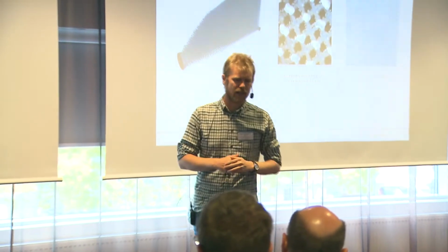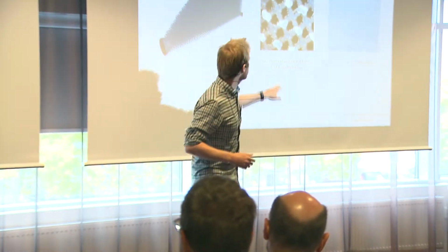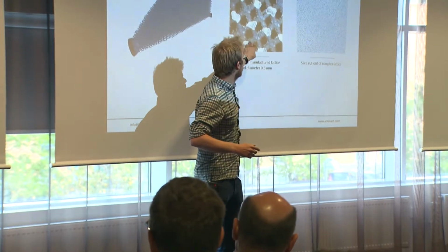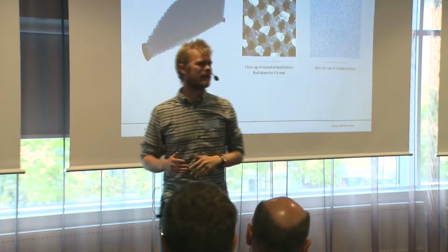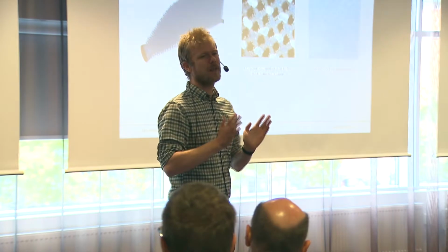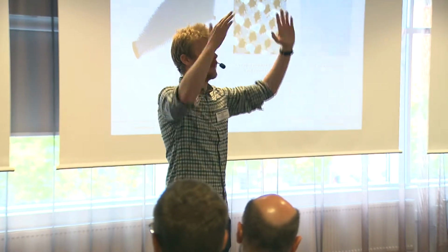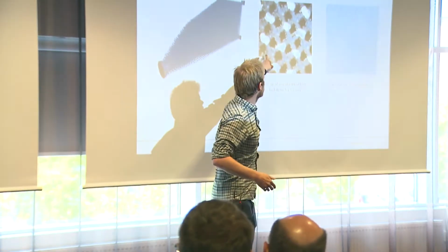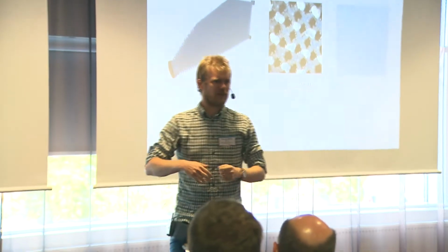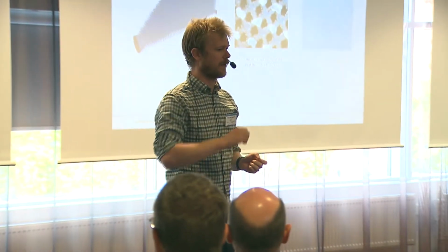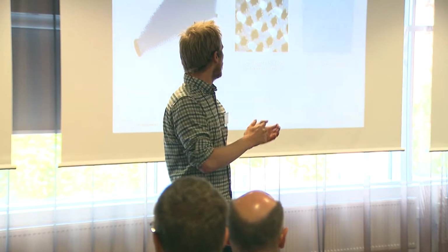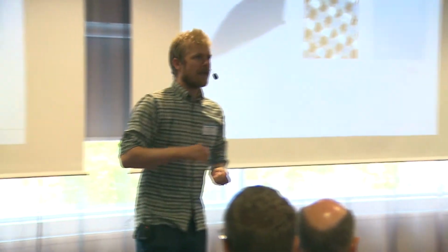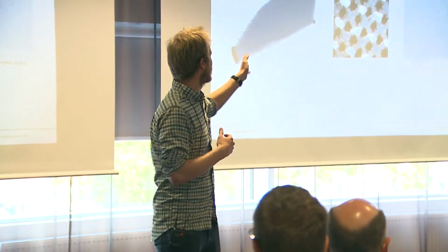So here's just a zoom in on a printed lattice, and one thing you may notice here is that we have a rod going here. It's 0.6 millimeter in diameter, and it's not a straight rod. I mean, the precision of the machines and the surface quality makes the rod go like this. And this is the perfect recipe for making stress concentration in certain places, which are going to be really good places for crack formation. And then what you get is actually pretty poor fatigue properties of your lattice structure. And that's just for testing the lattice.